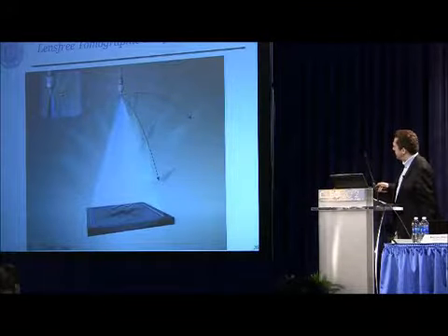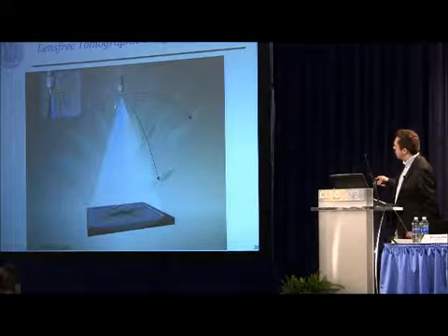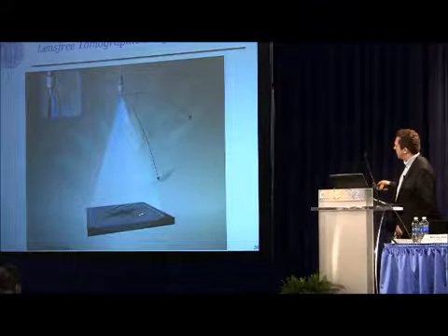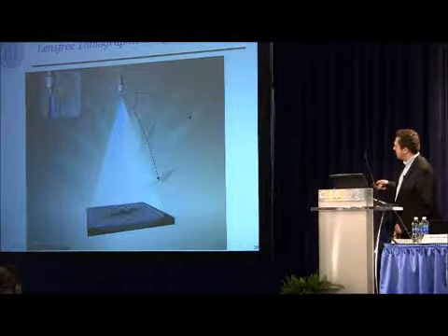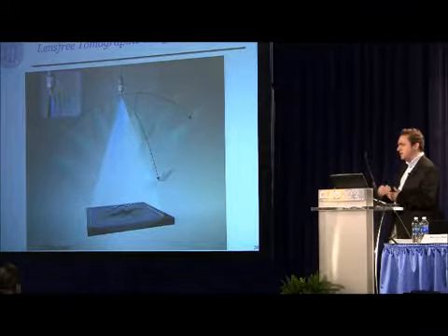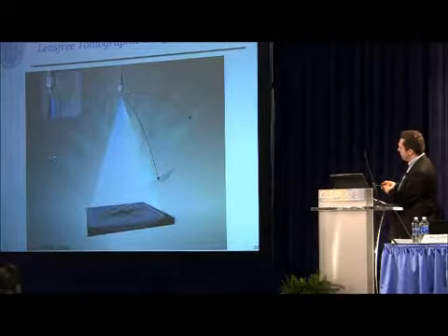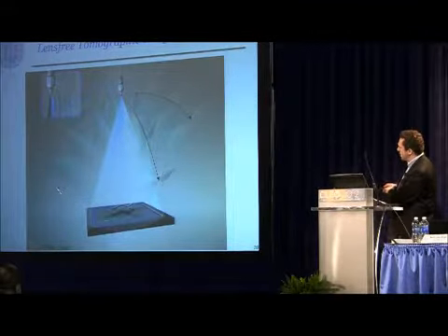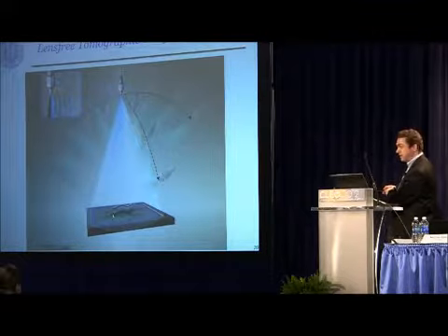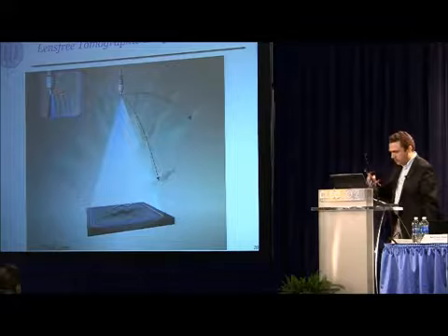And we've shown that you can do actually more interesting stuff. Instead of a single projection image where we capture the transmission microscopic features of a sample, you can do something very similar to X-ray computed tomography, where you take a light source and rotate it, and at each point here you slightly jitter the light source so that you synthesize a super result holographic image, and this way you can synthesize a tomogram of the animal or the cells.